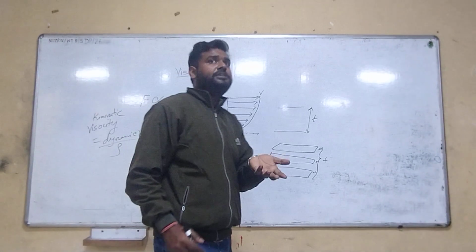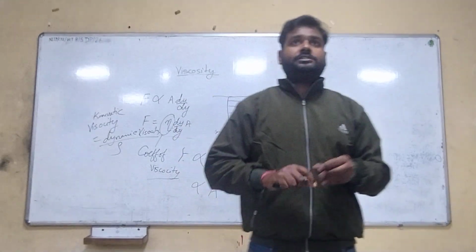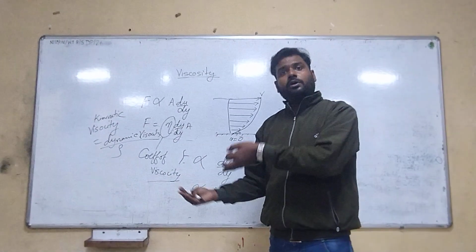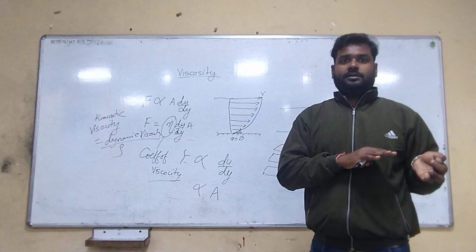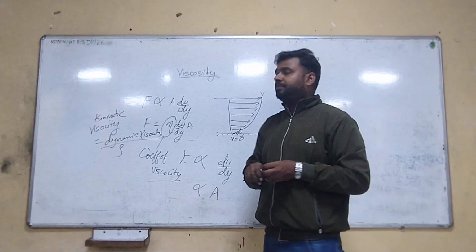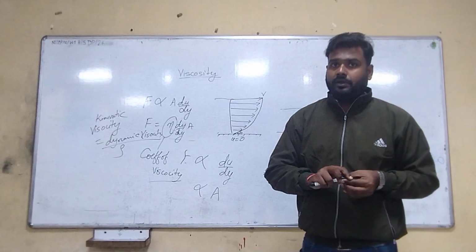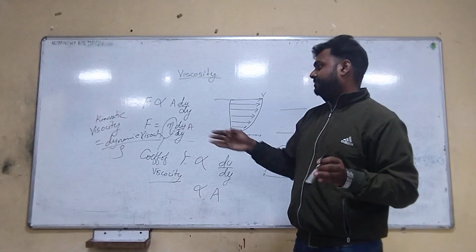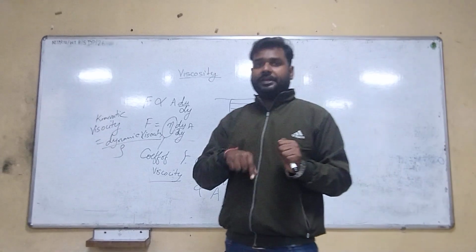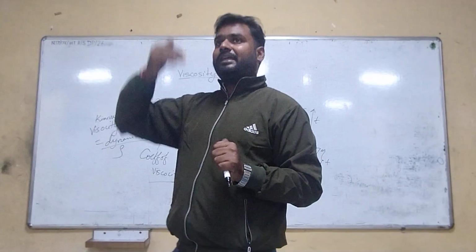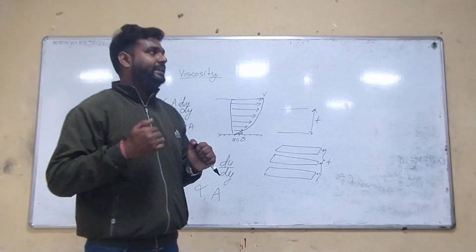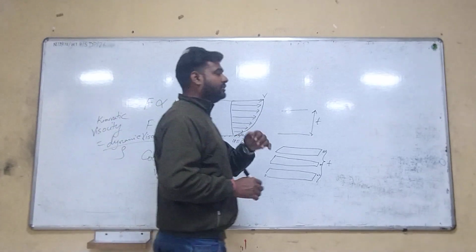It also depends upon the density of the fluid. The more the density of the fluid, the more the kinematic viscosity. Dynamic viscosity doesn't depend upon the density of the fluid, but it does depend upon the temperature. As we increase the temperature, the dynamic viscosity decreases.